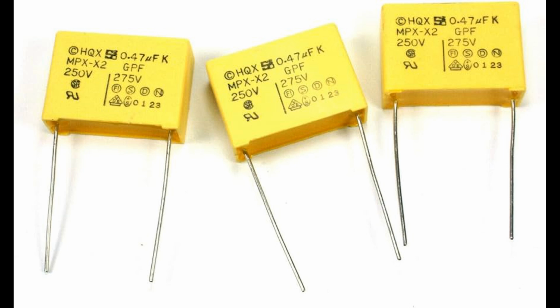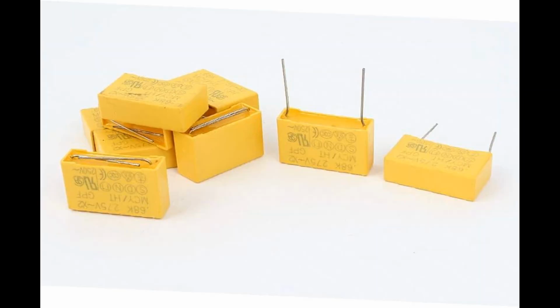11. X and Y capacitors for safety applications. X and Y capacitors are a specific category of film capacitors used in safety-critical applications, especially for EMI suppression and power lines. X capacitors are used between live conductors, line to line, to filter out high-frequency noise. Y capacitors are placed between live conductors and ground, line to earth, for safety purposes, preventing high voltage from leaking into the system.